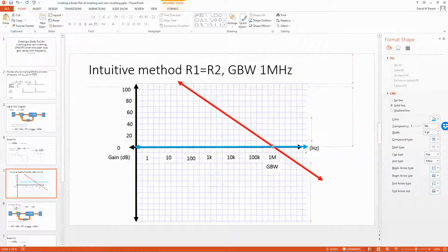So if the gain were 0 dB, an approximation I could put is this line. I get 0 dB, and then I asymptotically follow the integrator model, right? If I calculated a gain of 20 dB, I could just do that, and it will come here.